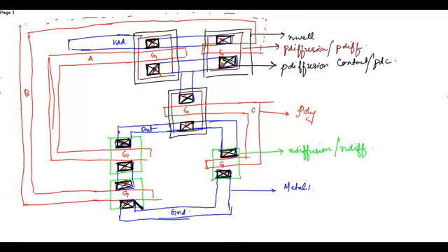Why? Contact word means that you have to make a contact. Normally the metal layer just overlaps, but it is not connected. So in order to connect, you place the diffusion contact. So this is the N diffusion contact or the NDC.